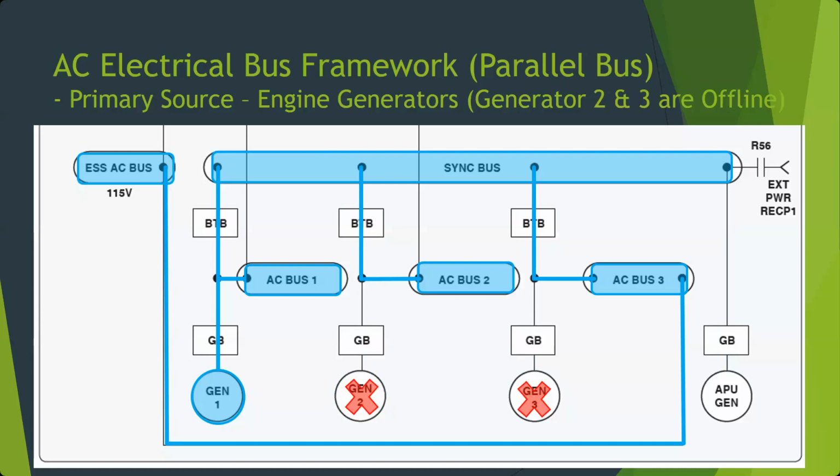The 727 doesn't have it, but today you don't need the in-flight entertainment system if you're down to a single generator. You maybe don't even need the main cabin lights. You can switch to just some emergency lighting. Maybe you don't need all the displays in the cockpit. You can shut off displays. Now, the nice part today, everything going to LED and flat panel displays, they don't really use that much power. But you might shut down certain things in order to reduce the load. That's called load shedding.